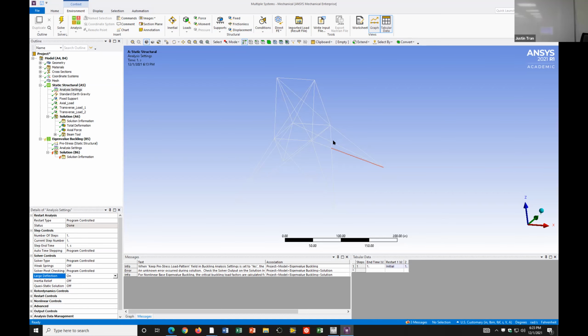Most of the time you're only really interested in the first one because that's the one causing the break. But if you do have a situation where you apply a huge amount of load at once, then the shape of the structure will get lifted. So that's the purpose of it. But you're right, most of the time you're only interested in the first, because if you go past the first one, you're not going to see the rest of the structure. Your structure is failing anyway, but the shape could be important too. If you're doing demolition of something, and you want it to break in a certain way, that could matter.